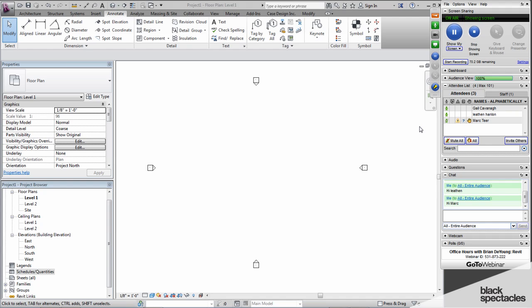Well, there's a couple of things that you might be experiencing with that. There are all kinds of different organization tools within Revit. One of them is what we've been talking about, work sets. Another one, and I use this technique quite often because I work on very large projects, is to divide up what is one project into multiple files. That would be different RVT files, yes, separate complete project files.